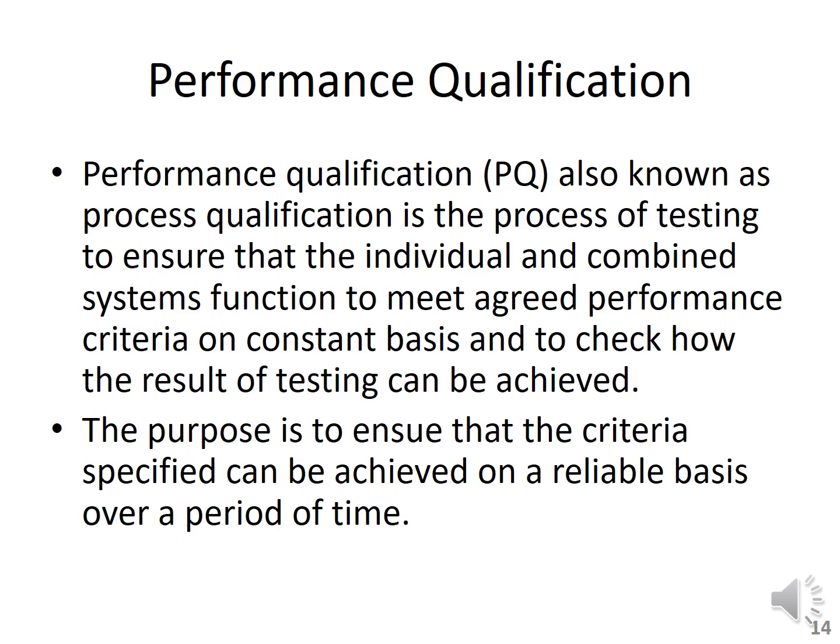Performance qualification. Performance qualification is also known as process qualification, and this is a main step or main phase of the validation, right? So this is the process of testing to ensure that the individual and combined systems function to meet agreed performance criteria on constant basis, and to check how the results of the testing can be achieved, right?